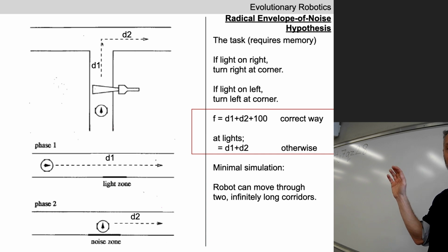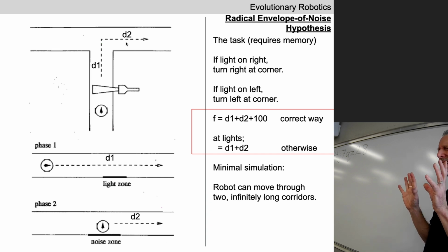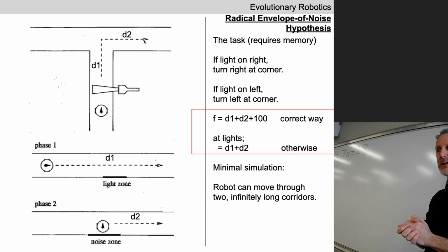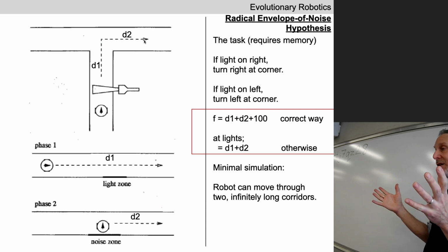And if this controller is going to successfully turn the robot in the correct direction, that controller should more or less ignore its noisy input at that time and turn based on either some internal information or possibly don't turn at all, just drive straight through this region and get out of this region and then start driving again in response to sensory information. We haven't talked about how a neural network controller can actually do this. You can try and evolve it for yourself.